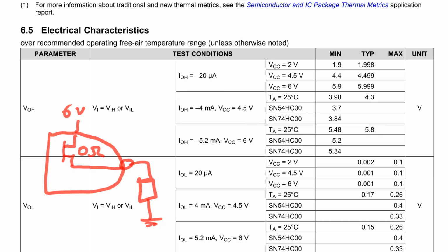So we're getting a 0.2 volt drop at 5.2 milliamps output current. So use Ohm's law. Oh, that's homework for you. Oh yes, there's the temperature I told you about, at ambient temperature. I forgot to mention that. So anyway, you can essentially work out the effective output resistance, in quote marks, of the MOSFET inside there. I've drawn a JFET, but it's actually a MOSFET, and the output resistance of that at various currents. That's why the difference in this voltage here is going to get higher and higher the higher your output current gets, up to that maximum.